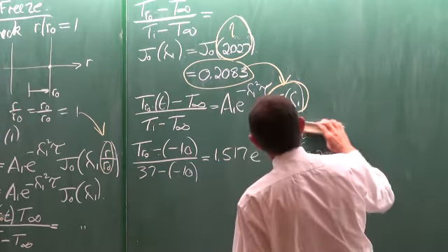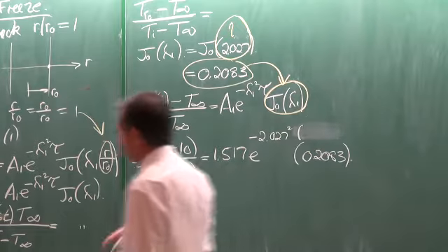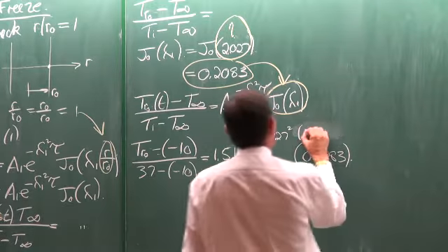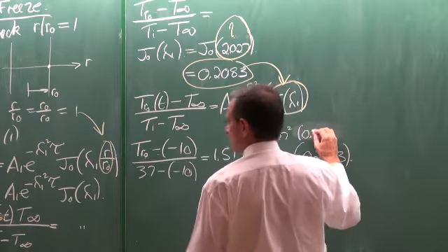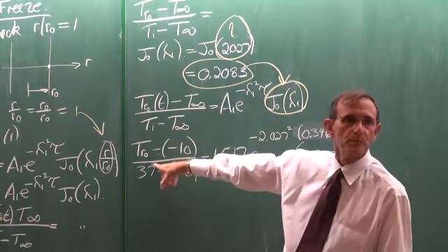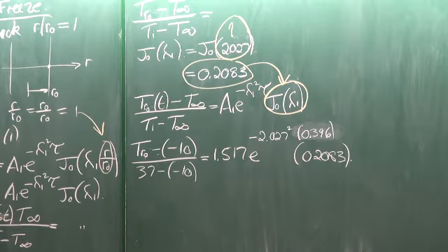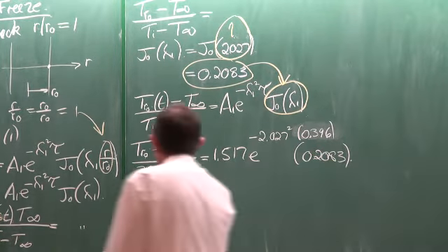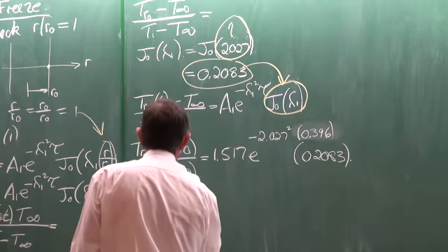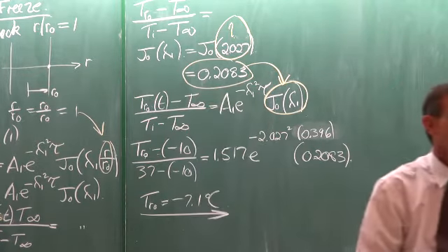Sorry, I've made a mistake. Obviously, we want to calculate tau now at this value, at 12.2 hours: 0.396. Otherwise, we have two unknowns, the temperature on the outside and tau. So this temperature that we now calculate is equal to minus 7.1 degrees Celsius.